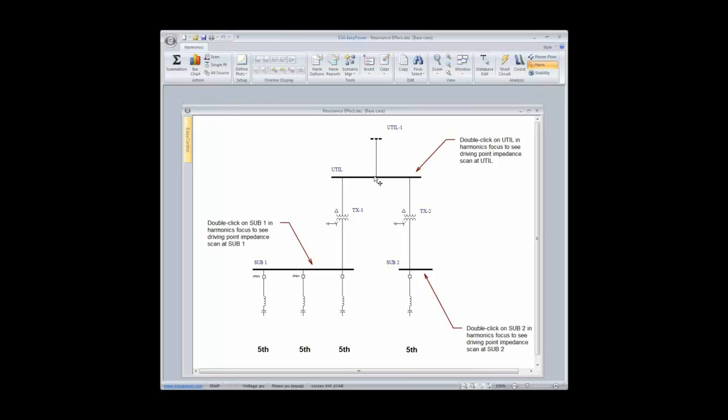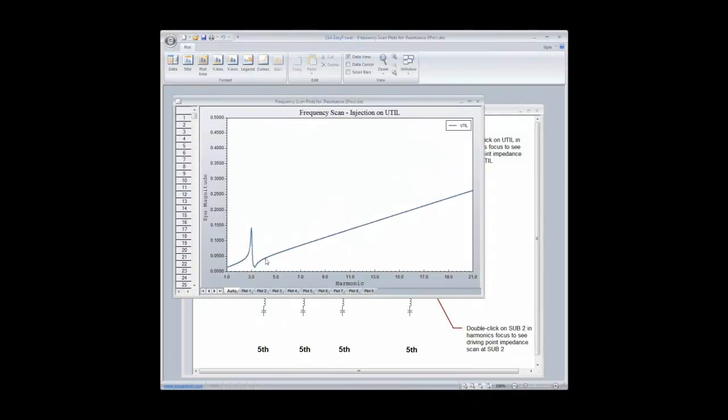So a key item in notch harmonic filter application is going to be buffering. And here we have a clear, good reason that we can apply a filter down on this location. We may have, for instance, a load down here that we want to reduce the distortion going out through the transformer. In that case, we have this buffering impedance. And if we do a driving point impedance scan, truly, we do see, yes, the effect of the filter is minimized, and on top of it, where it's tuned and it resonates, those points are being shifted.